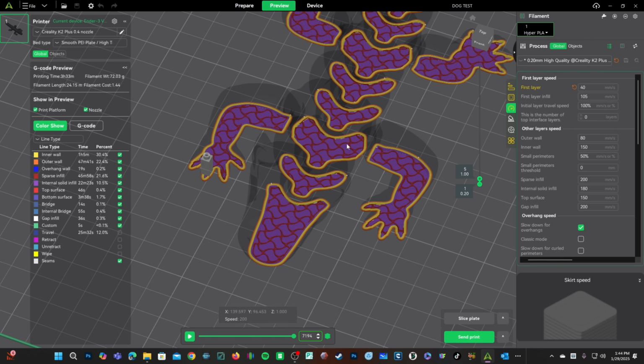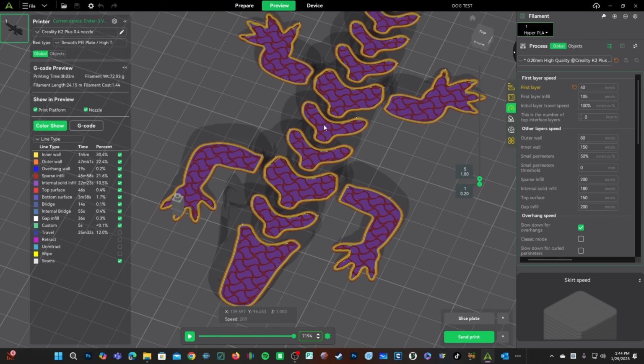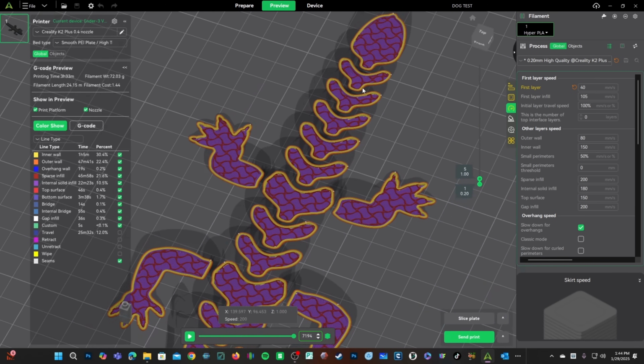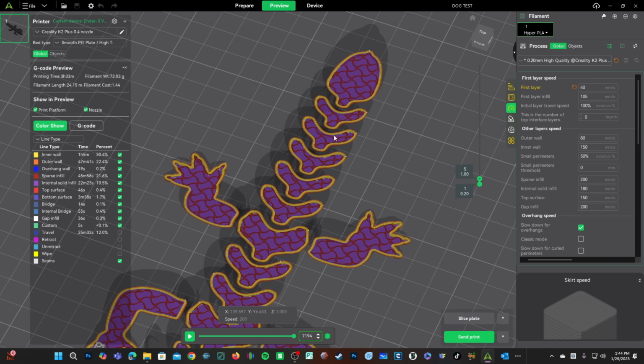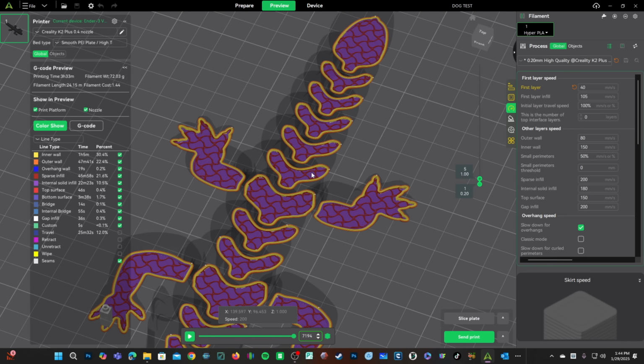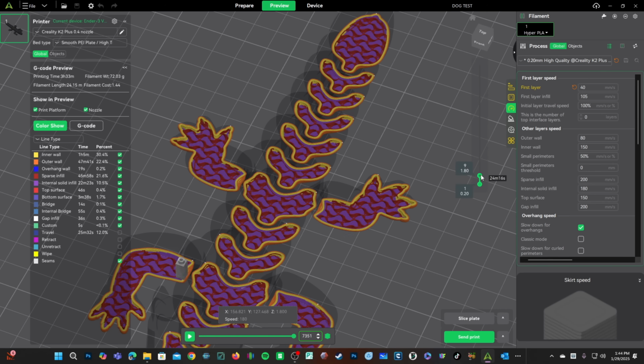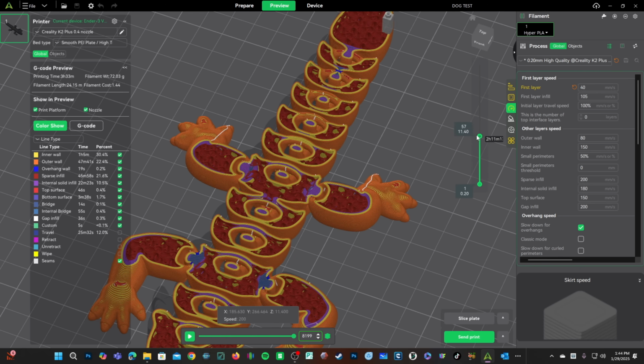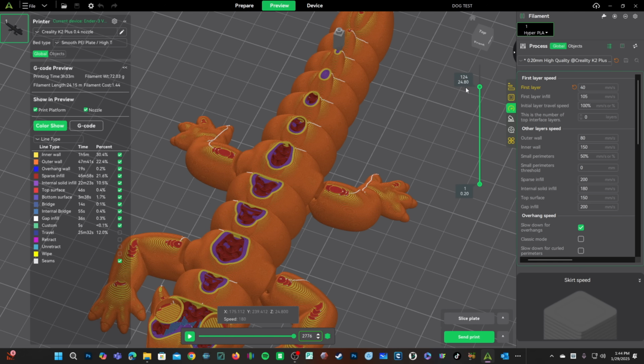This first layer of infill can pull, tear, rip, or remove one of these small features clean off the bed. However, once that first layer of infill is down, you now have strength for which the printer can ramp up its speed and continue the rest of this print based on that strong, solid foundation, allowing it to move faster.